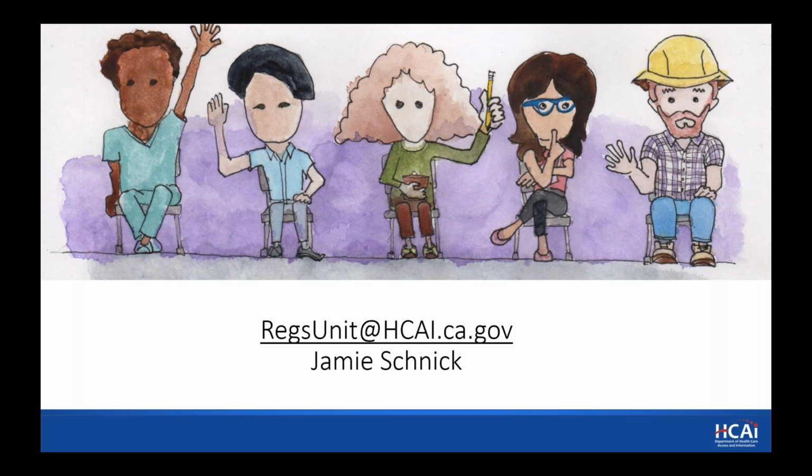Thank you, Jamie. I'll say this, let me keep it going. Foreign systems, the area above the dedicated space required to be kept clear shall be permitted to contain foreign systems provided protection is installed to avoid damage to the electrical equipment from condensation, leaks, or breaks.